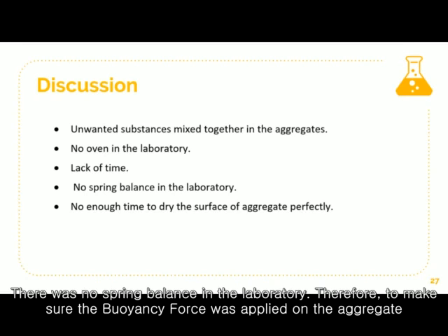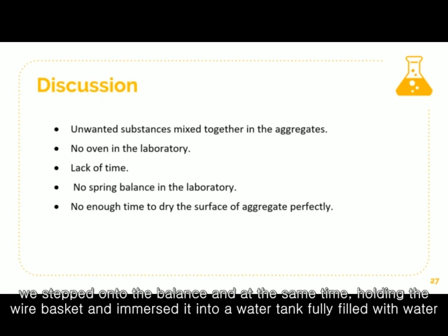There was no spring balance in the lab. Therefore, to make sure the buoyancy force was applied on the aggregate, we stepped on the balance at the same time holding the wire basket and immersed it into a water tank fully filled with water.